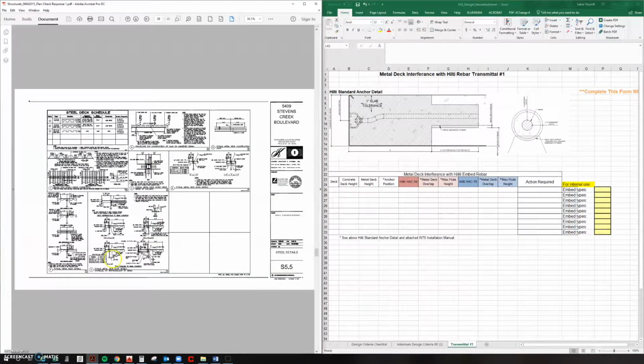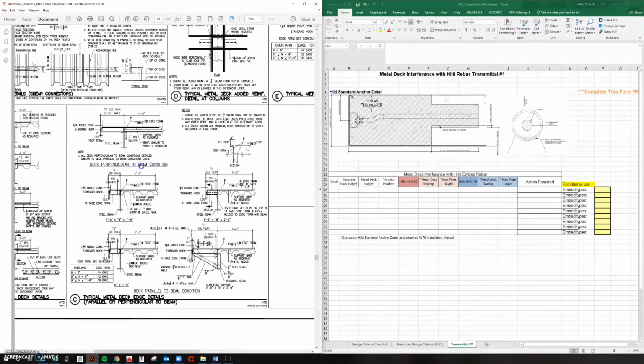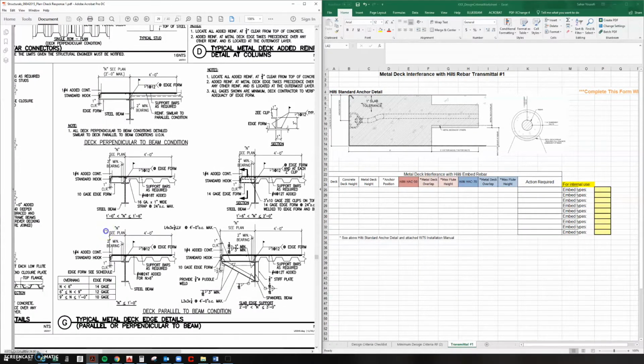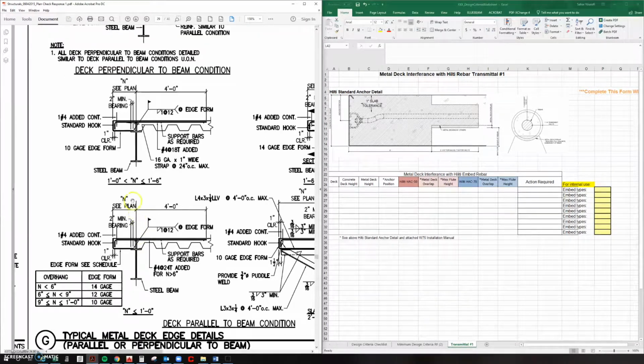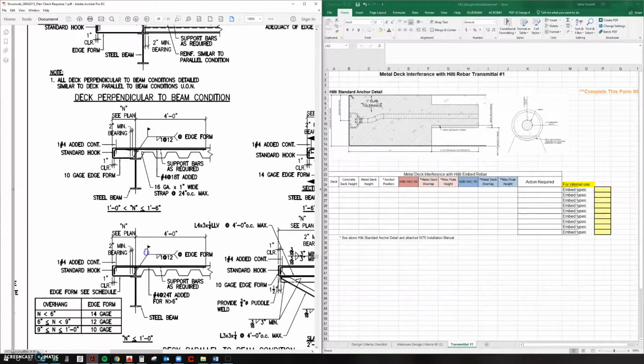Open the Structural Specification Review pages saved in the Specification Review folder, or you can open the structural drawings. You will use the deckage detail to determine if the metal deck occurs at the location of the rebar. In this example, the metal deck begins at a distance n from the edge of the deck. Review the plans to find the distance n.